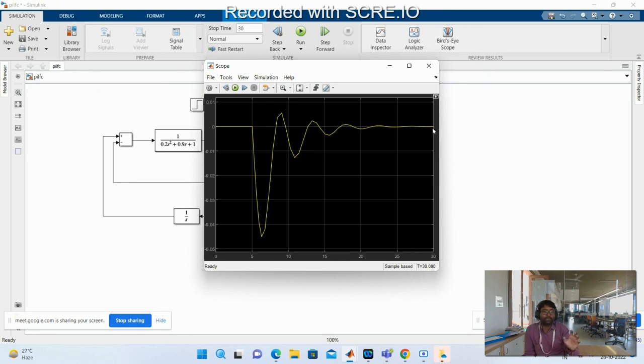So with the PI controller, when the demand is increased by 0.01 per unit, initially your frequency will drop, and how much it is dropping will be fed back to the speed changer through the PI controller. Then your speed changer will slowly open up your valve position. Then more steam will be flowing, and your generator will speed up, speed up, and again you are maintaining the same normal frequency with the frequency deviation equal to 0.